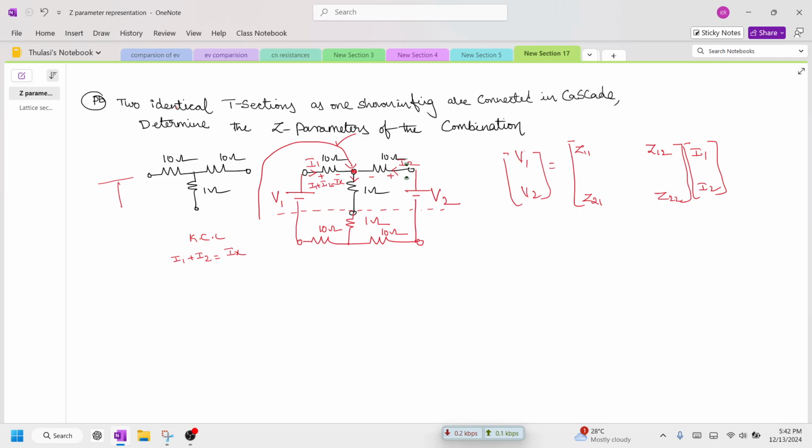Now we need to find out this current. So this is flowing across the branch, positive as well as negative. These two are once again connected in series. And here in this branch, only I1 current will be flowing with the polarity of positive, negative. And in this branch, once again it gets divided as I2, and the entering is positive, leaving is negative. The net current in this branch is I1 plus I2. So in order to get the standard equations, we are going to get from here.